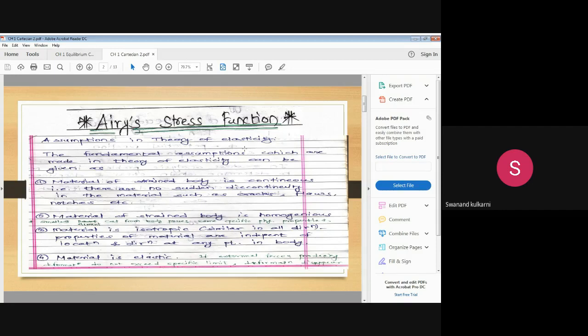Then the same equation of the unbalance we applied for this three-dimensional figure, and by applying this equation to the three-dimensional figure, we got the equilibrium equation, which is ∂sigma xx upon ∂x plus ∂sigma xy upon ∂y plus ∂sigma xz upon ∂z plus capital X is equal to 0. This was considered to be the equilibrium equation. Secondly, we identified the equations of the strain components: what is epsilon xx, epsilon yy, epsilon zz, epsilon xy, epsilon yz, and epsilon xz.